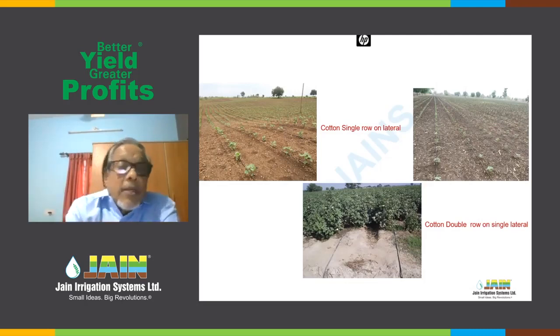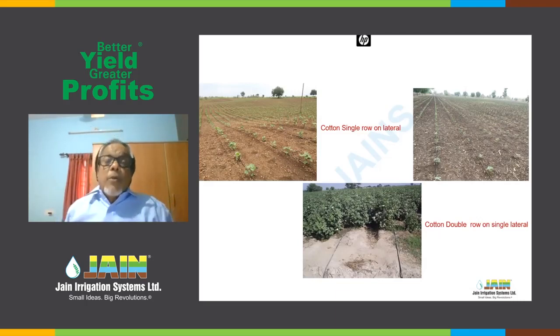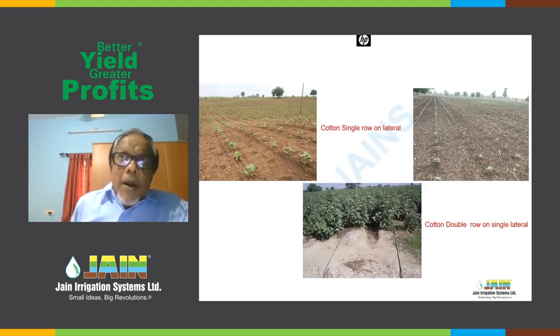But certainly on that left hand picture, it's not possible, because for the first 2 months, they will not get sufficient moisture. The more clay there is in the field, the more it is possible. The lesser the clay and the more Moram stony type of soil, cotton is quite happy to grow in such soil, but then the moisture spread will be limited. So giving 1 drip line per row is the requirement there, because of the rooting nature of the crop, the growth rate and the soil type.